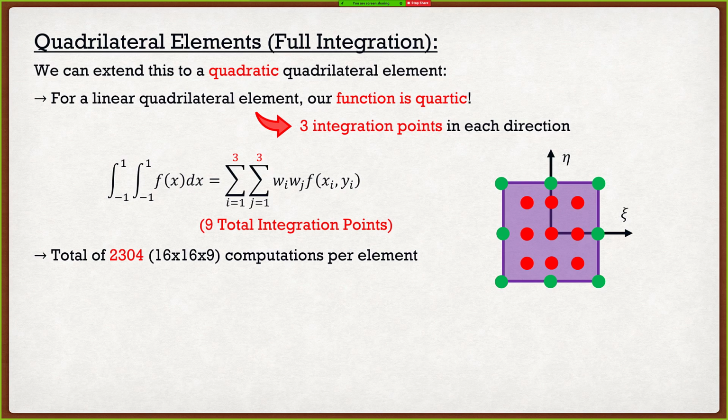So this is one of the reasons why, if we're switching between those sizes in Abaqus, it starts really increasing that computation time. It's not so much as double, but almost 10 times the computation time. Where did I get that number from? Well, remember, for a quadratic element, our stiffness matrix is 16 by 16, and each component of that stiffness matrix now has 9 integration points.